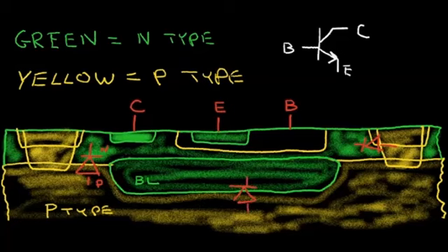So the collector region, which is this region of the buried layer, there's a parasitic diode, and I'm going to draw that on the transistor symbol. So we have this diode. And this, the wafer starting material, will be at the ground potential. So as long as the anode of this diode is at ground potential, it won't come into play and it can be ignored.